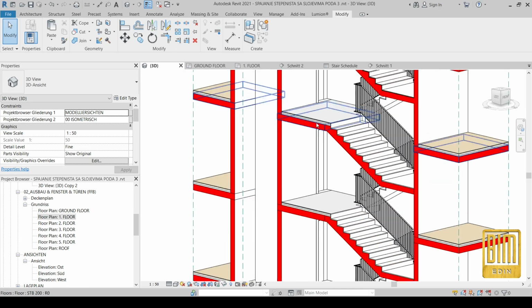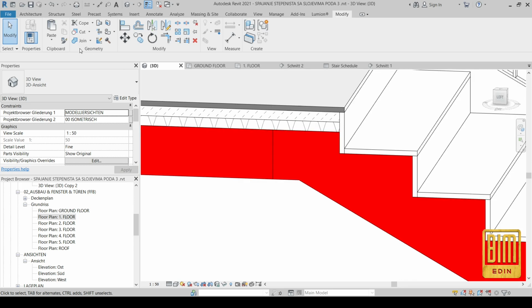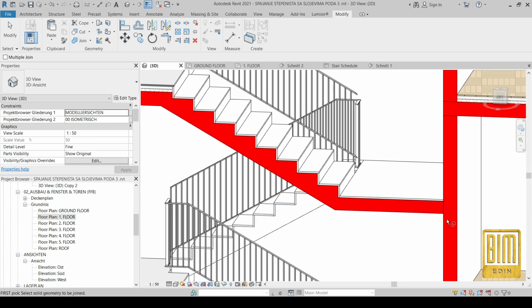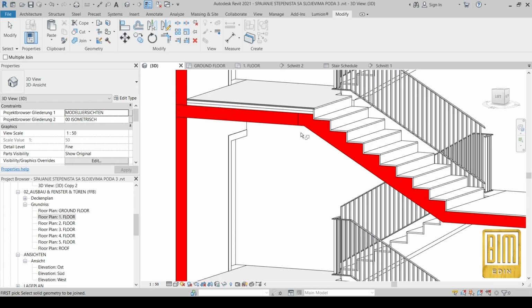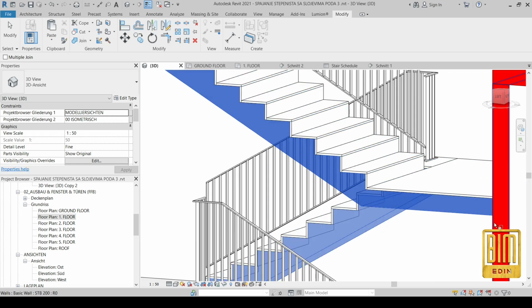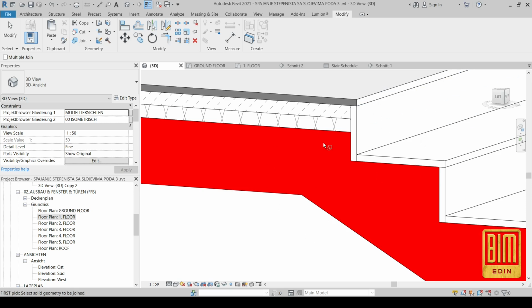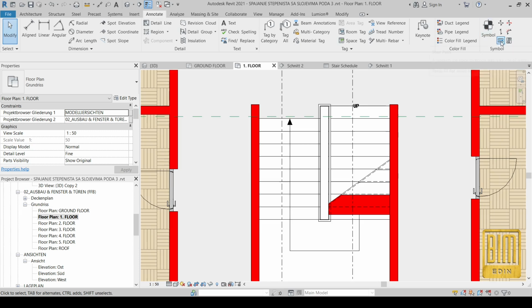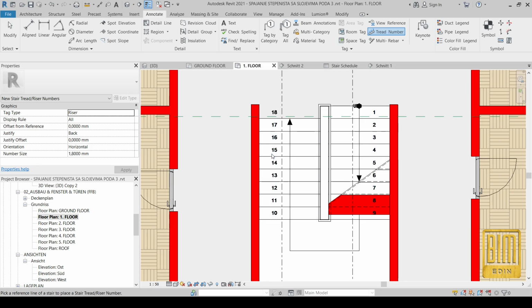Okay. From this side, it looks perfect. As I said before, every change we made on the section will appear in the isometric view. So when you create a presentation of your stairs, it will look perfect. You can see, and this is the reason why I made them from generic model in place. Later, when we finish this, we can change them from generic to stairs.